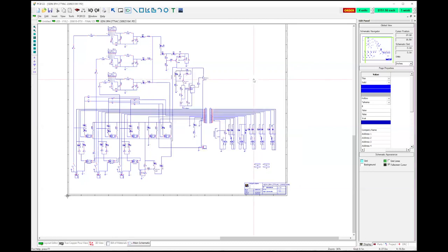If I use the manufacturer's part number to name the symbol and to name the footprint, and then add that information into the part number and such, then all I have to know about that part is that it is, for example, TCMT 1600. And anytime I want to place that part, I enter that string into the search, and it pops up.